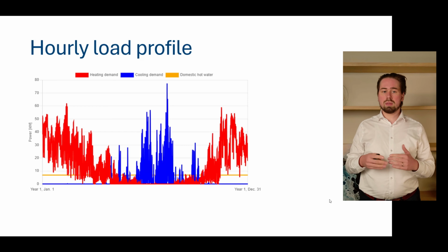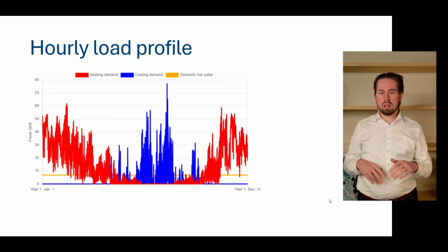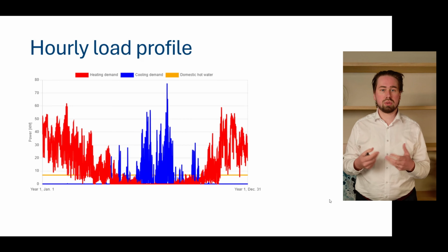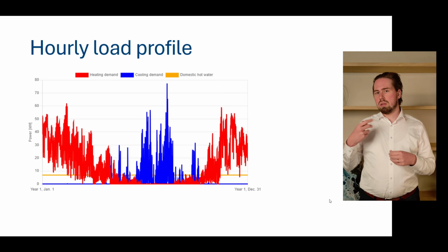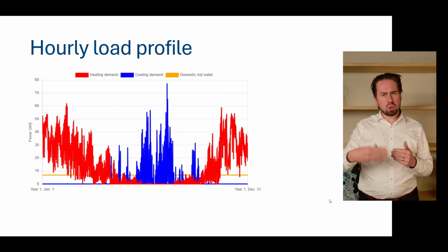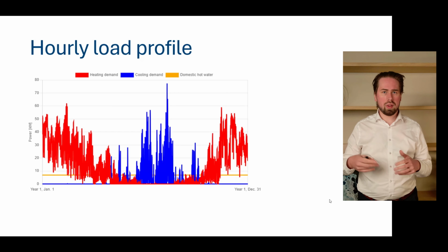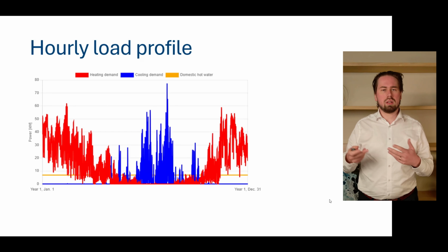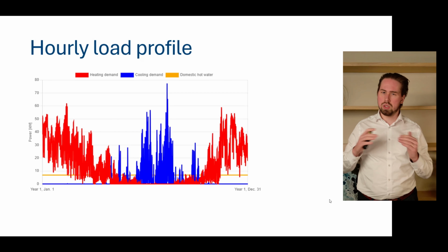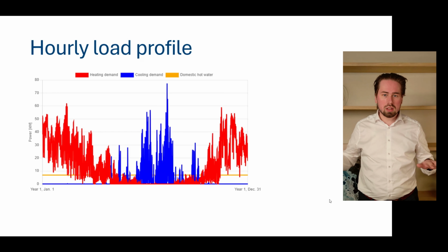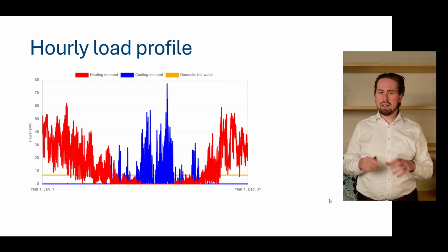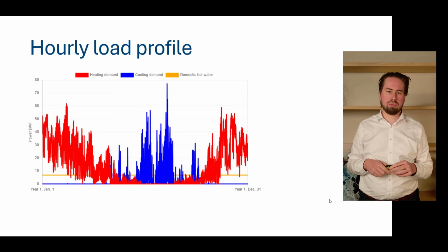Now in this example, which is for a residential building, you can see that our domestic load is constant. The load for domestic hot water is constant. Normally, this is also some tap profile, especially for swimming pools or hotels, buildings with quite a lot of domestic hot water demand. But in this case, you don't know when the domestic hot water will be, so we just assumed it to be constant, so it only contributes basically to the imbalance. And this is, for example, an hourly profile.